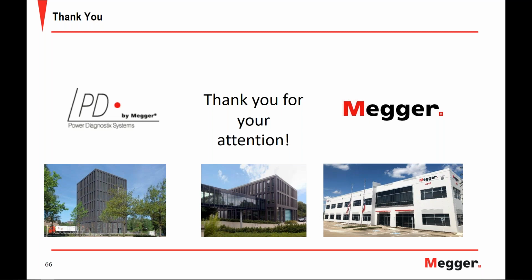All right, thank you. While I have you, what is the major difference between offline and online PD tests? Well, Michael, I think it was briefly explained in the presentation. Basically, with an offline measurement, your motor or generator is out of service and the power cables are disconnected and isolated. But what is more important is that your winding is at room temperature and you have a cold conductor. That means thermomechanical effects, which you can find in fact only during online measurements, you won't see immediately in an offline measurement unless there is already some decent deterioration of the insulation material.